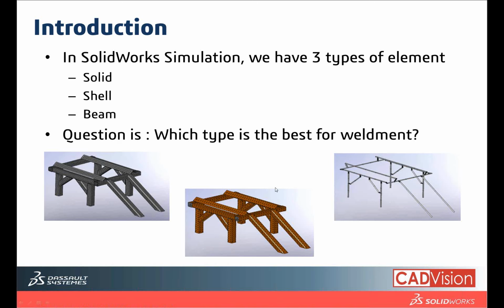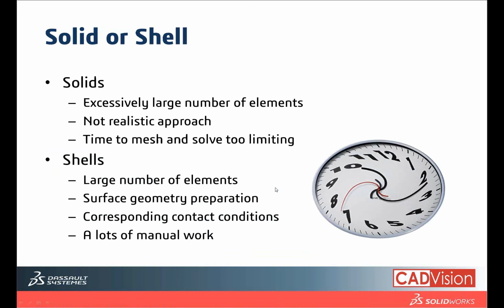So, solid and shell elements. Solid elements will have an excessively large number of elements. Not really a realistic approach when you are doing weldments, especially for very big or very complex frames, while it is time consuming to mesh and solve the whole frame's elements.